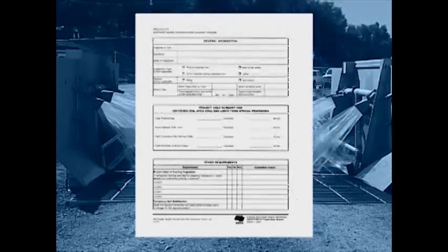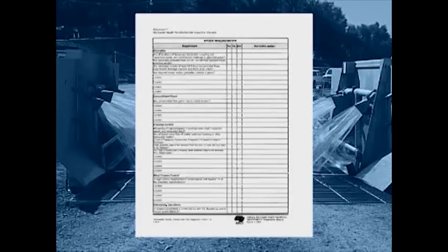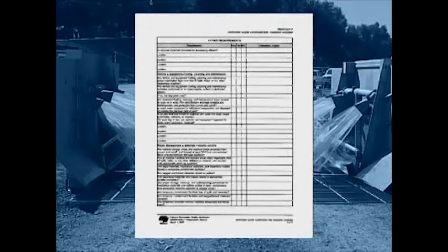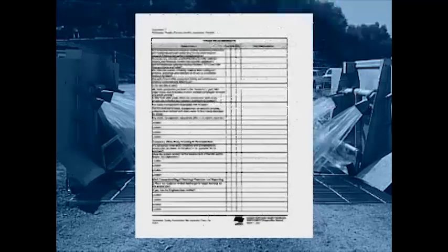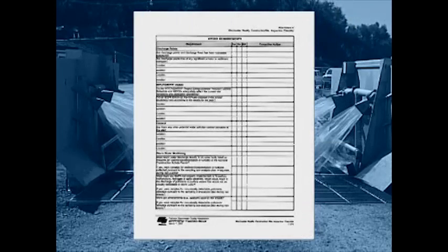Attachment H of the Stormwater Pollution Prevention Plan and Water Pollution Control Program Preparation Manual must be completed during each inspection. This checklist must be used for all inspections, unless the project special provisions require the contractor to use a different checklist.